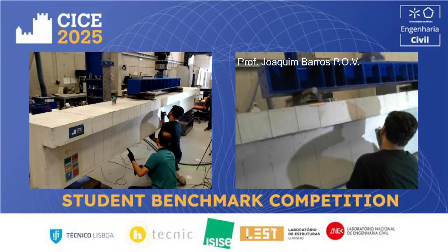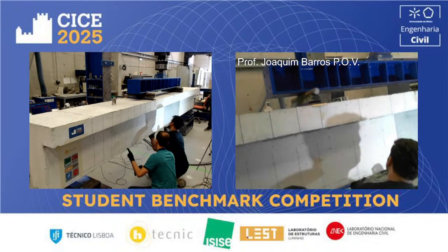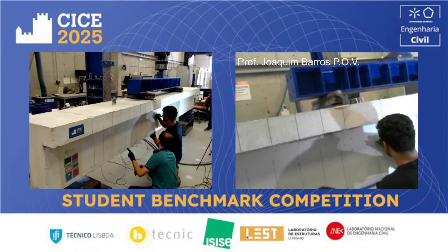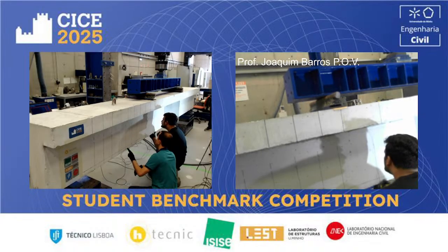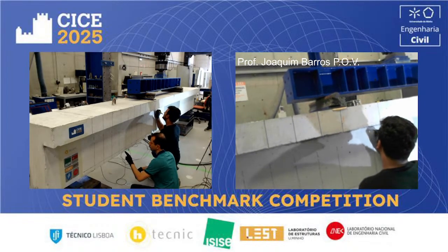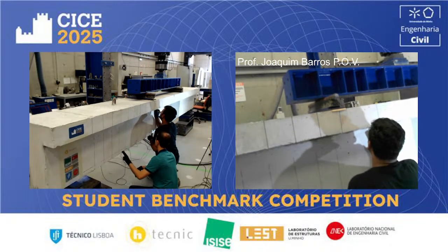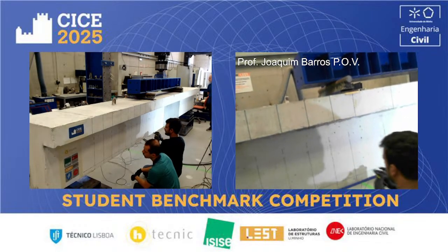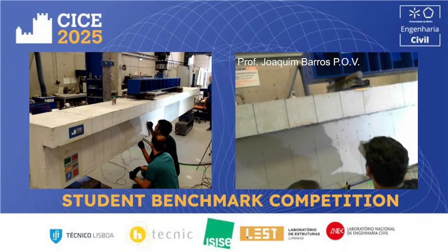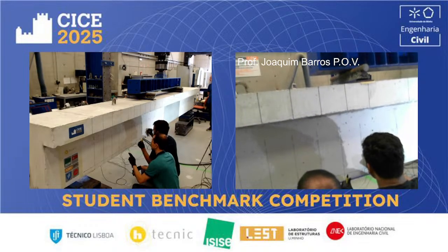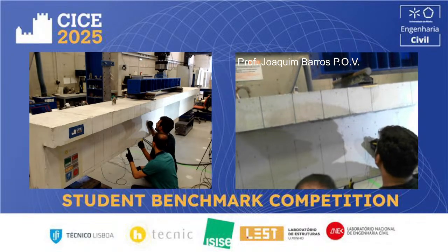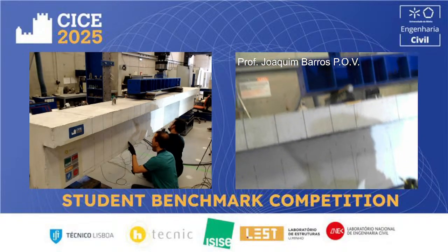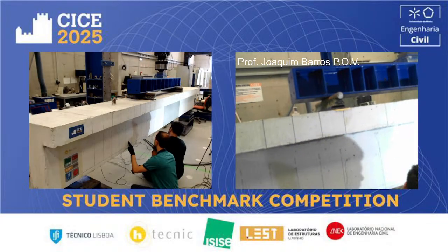85. So after post-processing the results, we will see that at this stage the stiffness in terms of load and deflection of the beam is decreasing due to this crack formation and propagation. So another crack now, at 90 kilonewtons, is in the location of the load section.